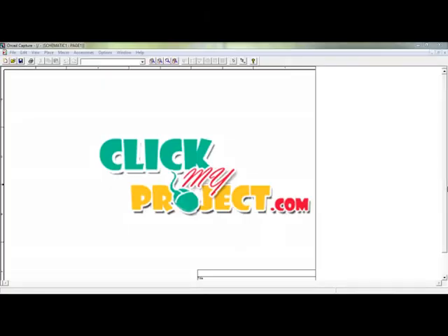Now I am going to describe the running procedure of our project. Here, the circuit displays the total overall MTCMOS basic switching bank circuit. Each base connection is connected to separately given time allocations to perform the delay performance. Here I separated each and every bank circuit by 10 nanosecond differences. For each 10 nanosecond difference, these bank circuits interchange their switching devices, and finally this is provided as an output waveform structure.